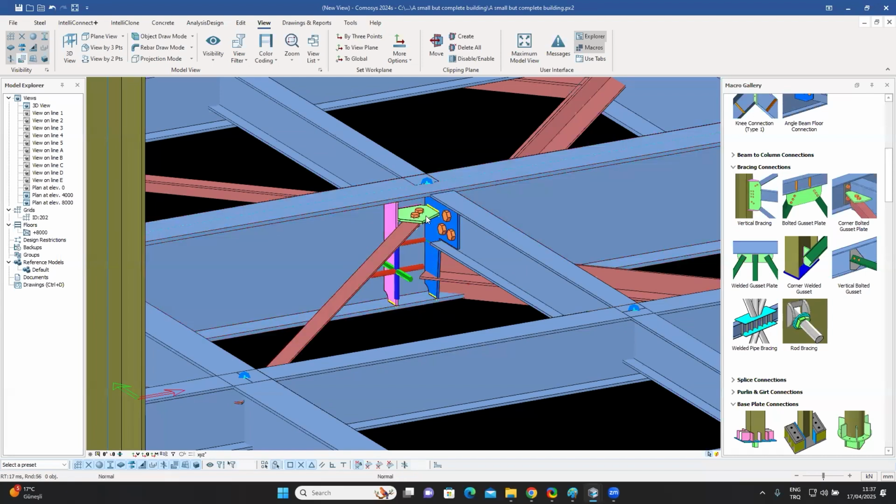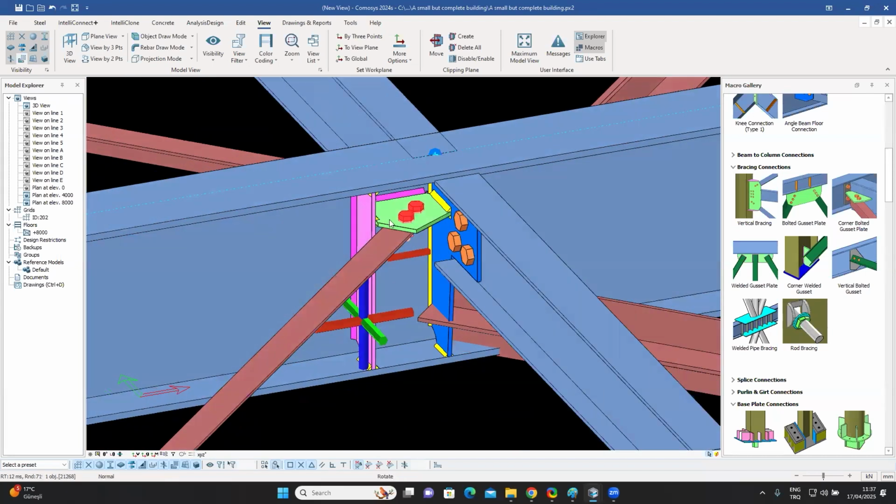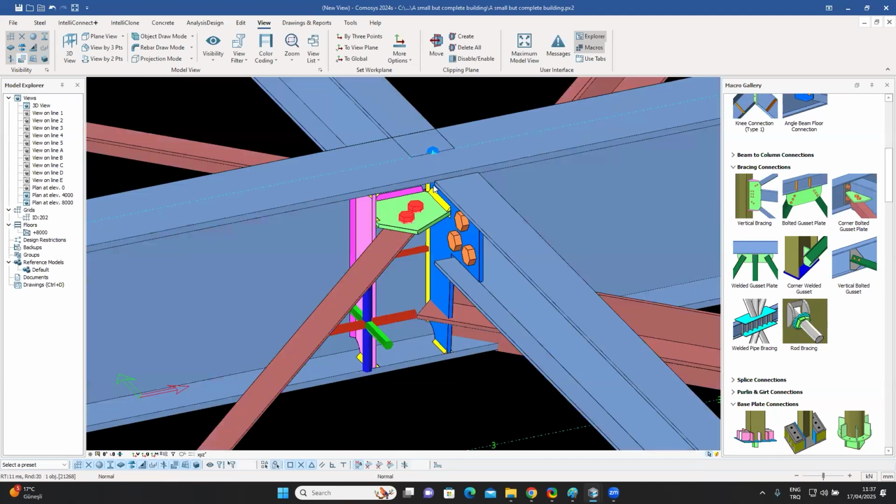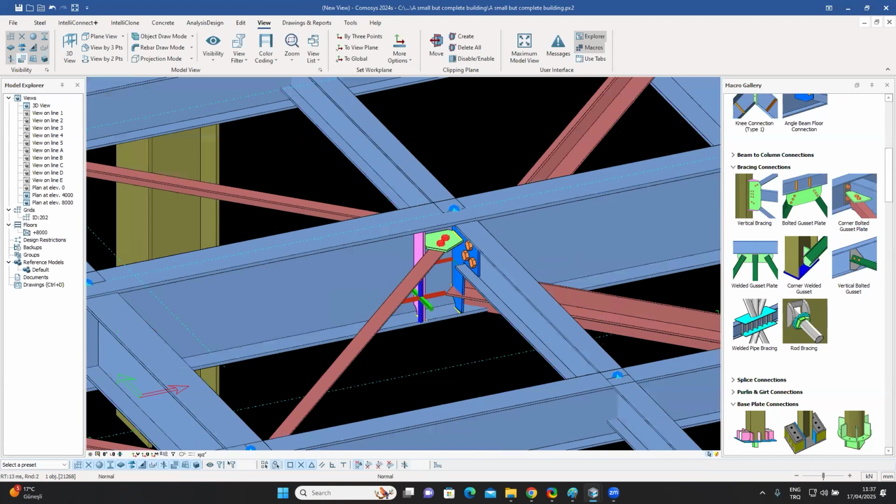And when you do that, you get this corner connection, which is very nice because you don't need to shift this at all. You can just directly use the fin plate, which already exists. But this might not be possible in all cases.